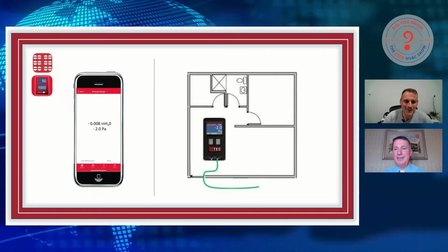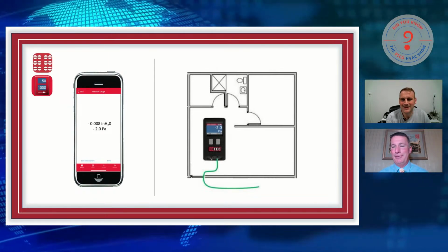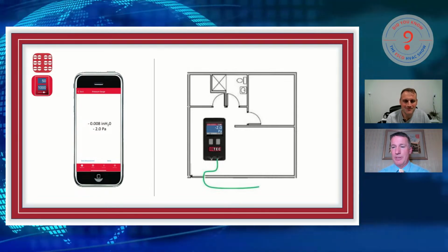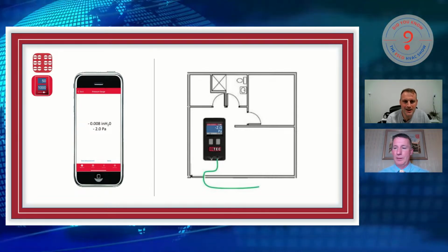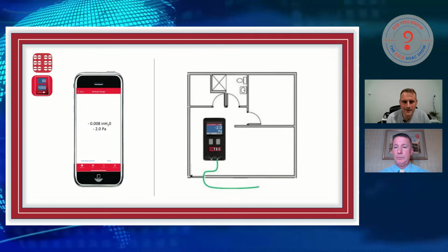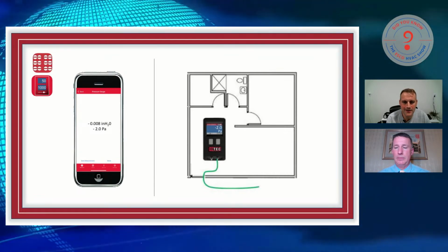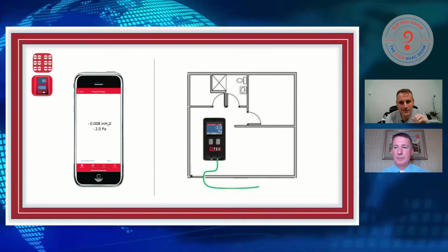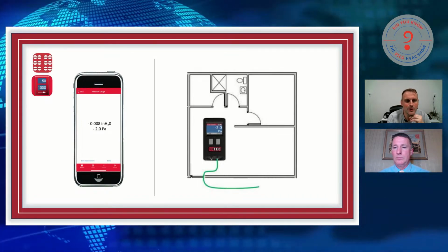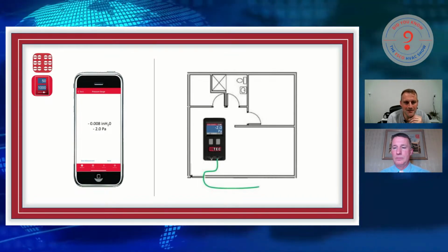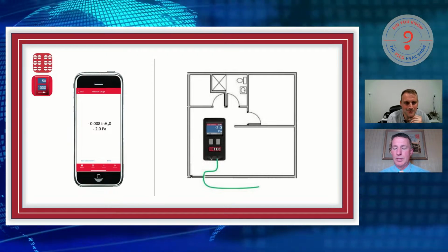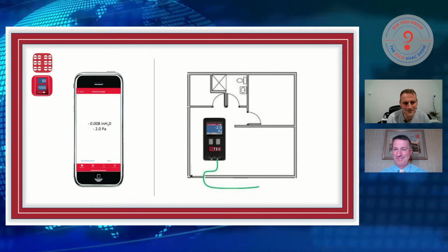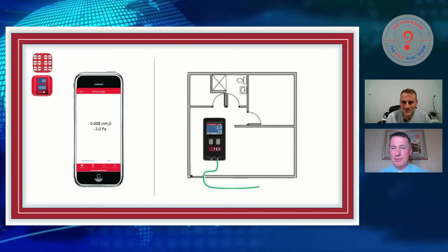I think so. There's a lot of evaluating what that number is representing. But when you fully understand how to do a dominant duct leakage test and you're confident with it, you will know that before you pull out, say, a duct blaster and go measure leakage, it's worth it, because you've already identified significant leakage with a dominant duct leakage test that took about a minute. And so you know you're going to find something. It's the blood pressure test before the stress test.